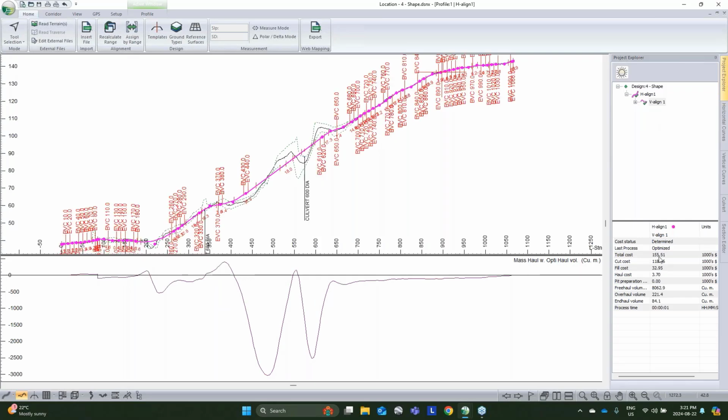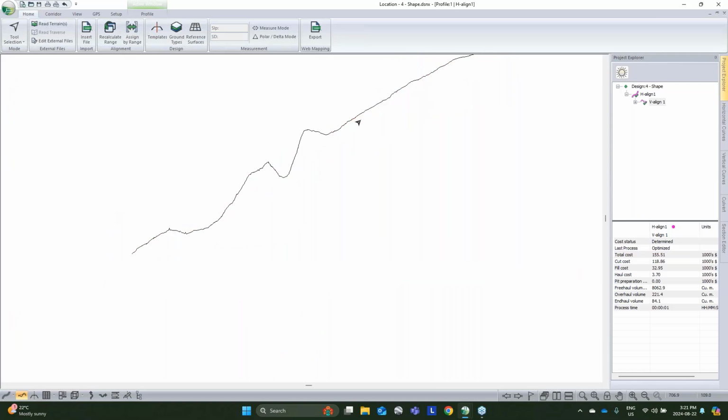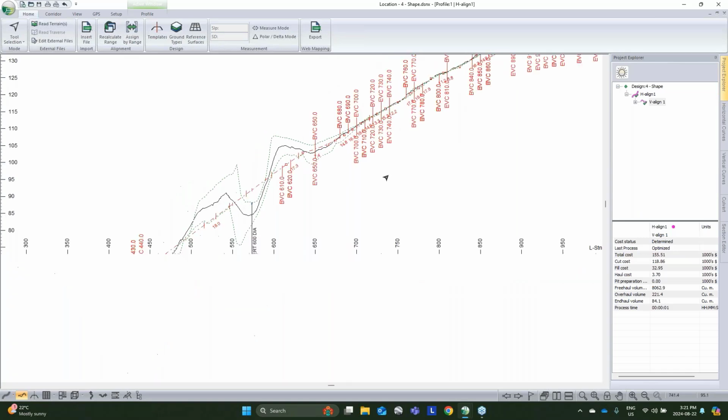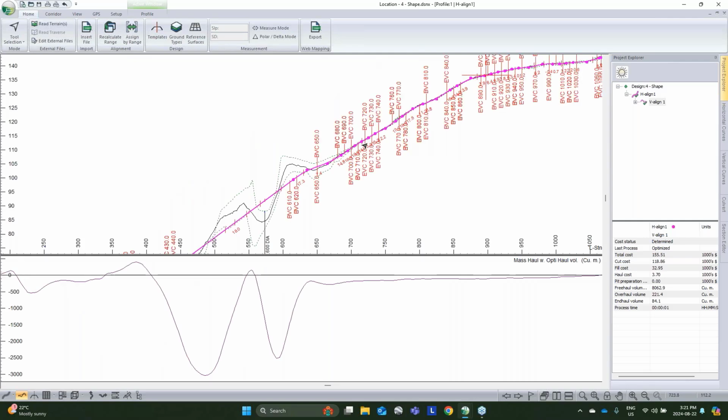So we can see our cost dropped a little bit without smart curves, but there is an awful lot of curves, and these curves, as introduced, are not saving us a lot of value individually, and they're certainly busy and a nuisance to deal with. So we've added that smart curve setting where we're eliminating stuff like this, where we've got a bunch of curves that are not saving much value.